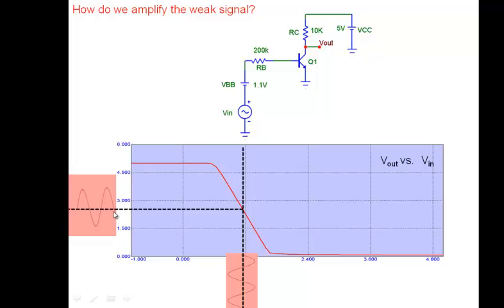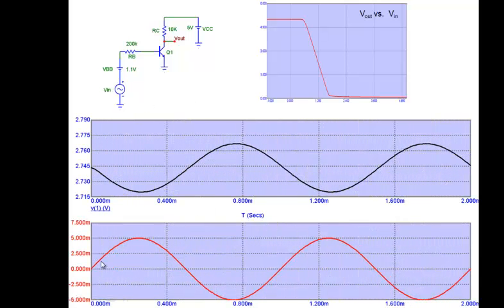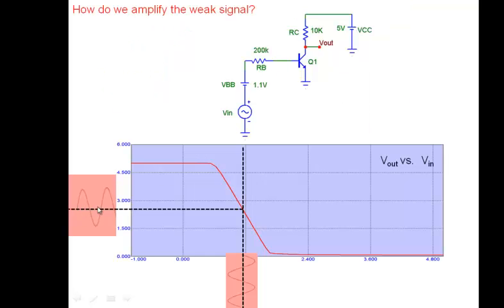Okay. Now you see amplification. You see that the signal that you've applied here appears here in an amplified form. Okay. So that's what we have here. Note that I applied 5 millivolt again. And at the output, what do I see? You can see that there's a DC part, and go back here and see that there is a DC part here.